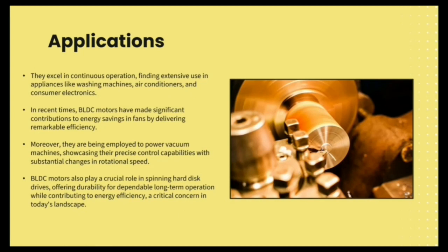We have seen that BLDC motors offer high efficiency and controllability, and that they have a long operating life. We already know that we are not using brushes, so we have a longer life. They are widely used in devices that run continuously. There is no spark, so there is a long life. That's why we use BLDC motors for continuously running operations.